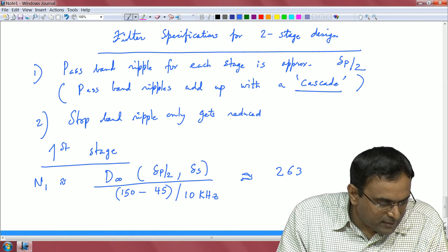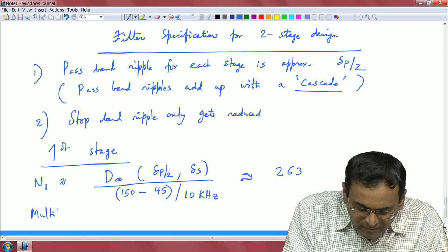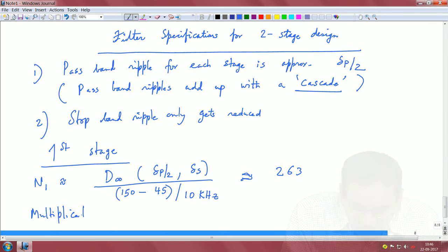And you could do your multiplications per second for stage 1 is equal to N F upon, again we will assume some factor 2 here, assuming that the filter is done efficiently. I will just mark it with a circle. If you are not comfortable, you do not have to use this 2, it is perfectly fine.